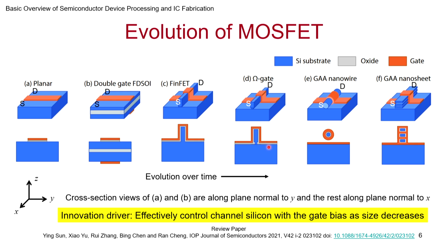But then why leave it that way? Why not go all around? So you have a gate all around. GAA stands for gate all around. So this was how it was envisioned. And indeed, that's the direction it has taken. Instead of making it circular, what they did was they just turned these fins in this direction, made them into narrow ribbons, nanoscale ribbons. And the nanoscale ribbons have, as you can see in the cross section diagram, a thin oxide all around with gate poly all around.